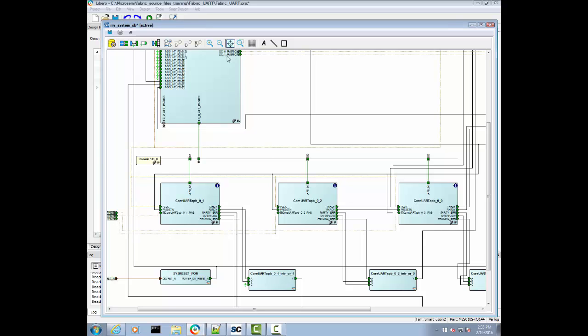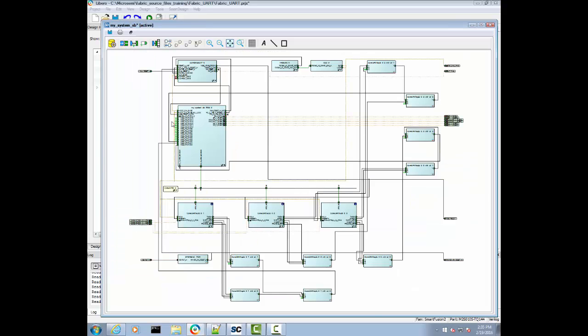So you can see that when you use System Builder, not only does it configure the microcontroller subsystem, but it puts all this other logic in for you. So you don't really have to think, oh, well, I want some UARTs, so how do I put them in, and do I need this block or that block? You just stay in the wizard, you say what you want in the Fabric, and it will put in all the logic that's needed. You don't really have to open this view. I just did it to show you that view.